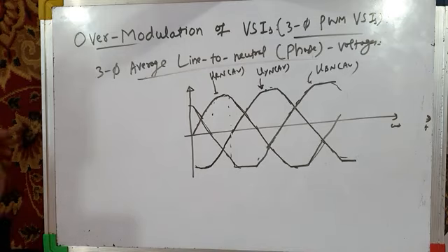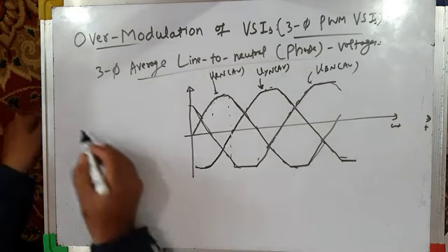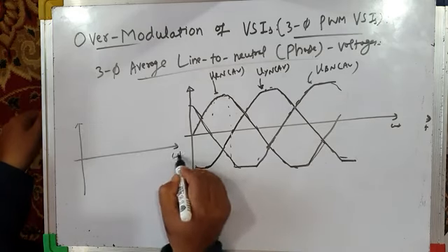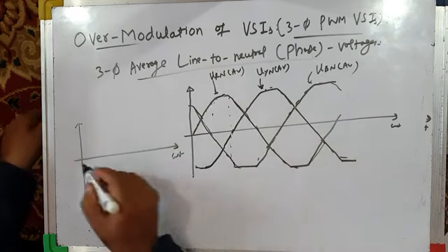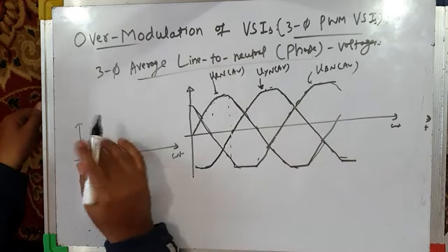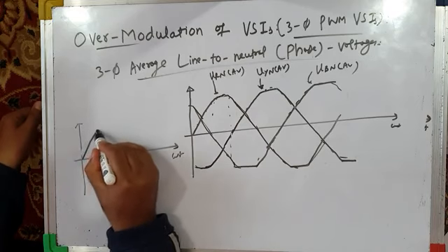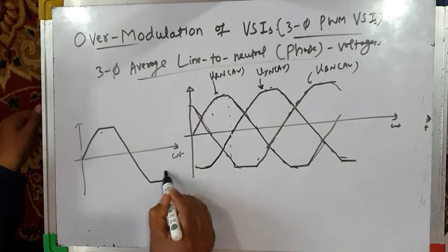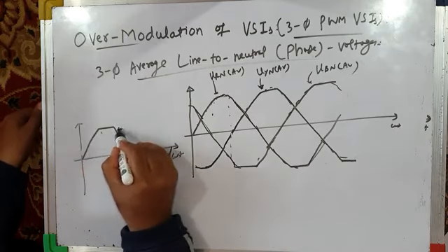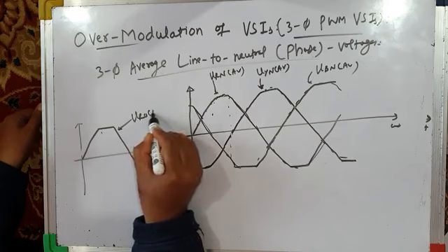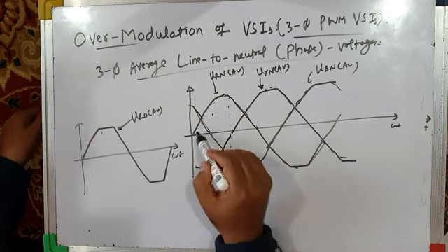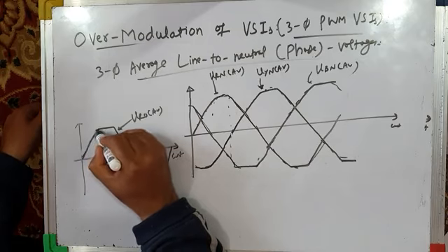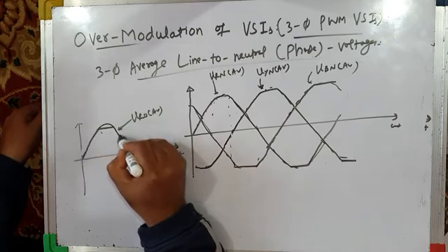Now, if you see the comparison between pole voltage, say pole voltage VRO, and phase voltage VRN, they are similar. For example, this is your pole voltage. Just a few moments back we have seen that this is our pole voltage, the average pole voltage VRO average, and your phase voltage is similar to this pole voltage. Only the amplitude will be slightly higher.